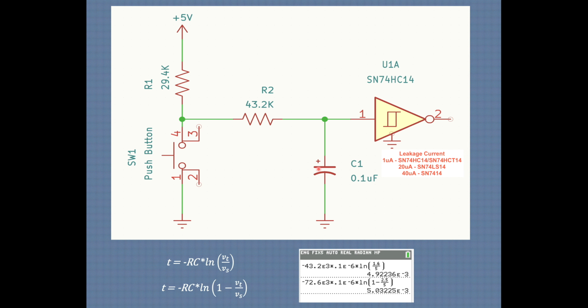Okay, another thing to be aware of when you do some of this: you want to keep your resistors around less than 40K. This one's a little high, sometimes, especially for a discharge resistor. Press the switch. This will go low to ground. And normally if you have no leakage here, this should be ground potential, or 0 volts, here.